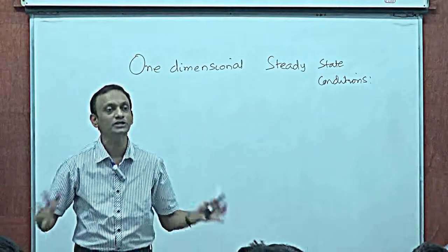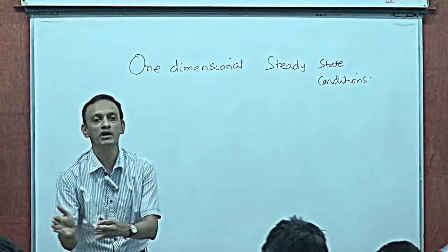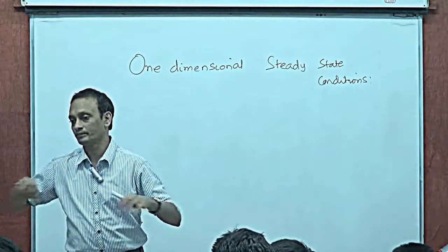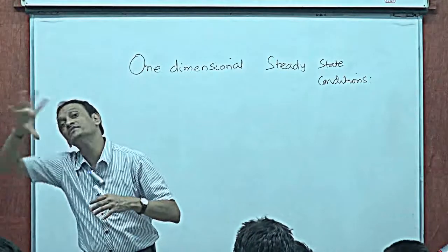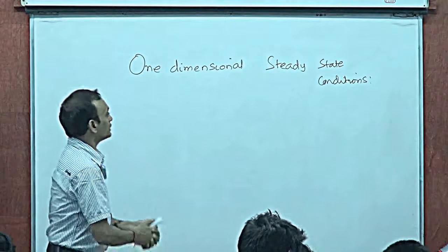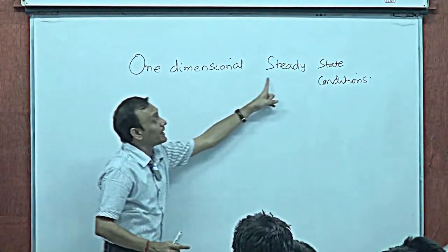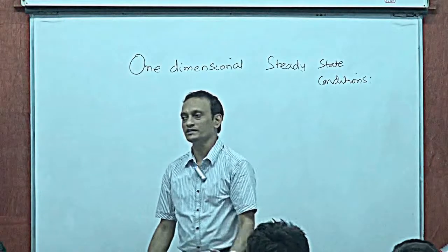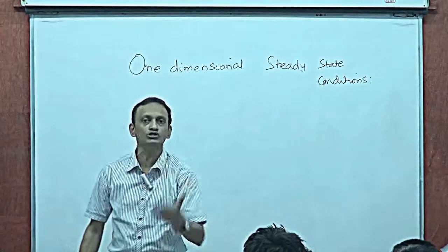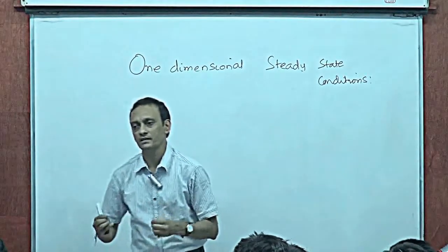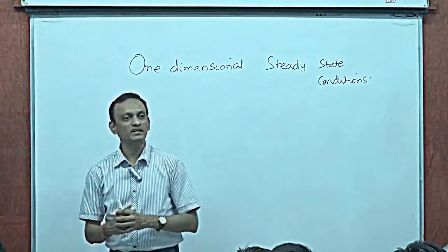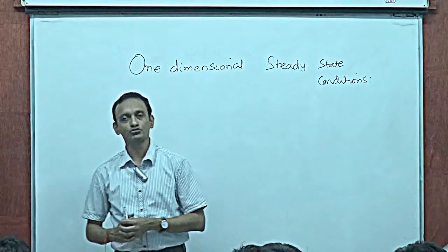When I say one dimension, it means one variable characterizing the flow, that's one dimension. It doesn't necessarily mean heat flowing along a straight line. It could be flowing in different directions. Even then, it might tantamount to a one-dimensional heat flow problem. So, one-dimensional and steady-state conditions to begin with. We might take a little bit of a detour and get into transient conditions also for heat flow, but a simplistic model so that we have a hands-on understanding with the basic equations and stuff related to heat flow.